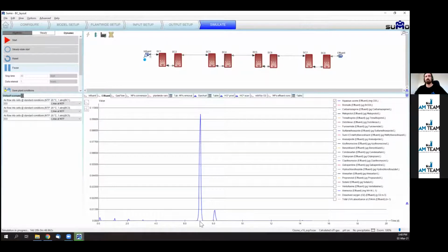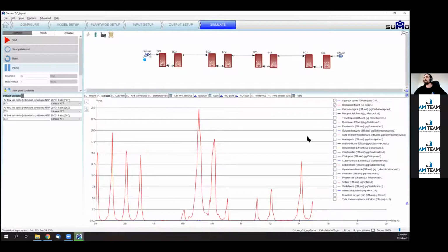because here we are just blowing without control a certain amount of gas in the 3 columns. We are splitting the dose, but we are not efficiently controlling the dose. So in this case, the dose of ozone might be excessive, and you get residuals. These low residuals, apparently not even measurable in an effluent, will affect the bromate formation and the whole installation. So this has an important effect in design.